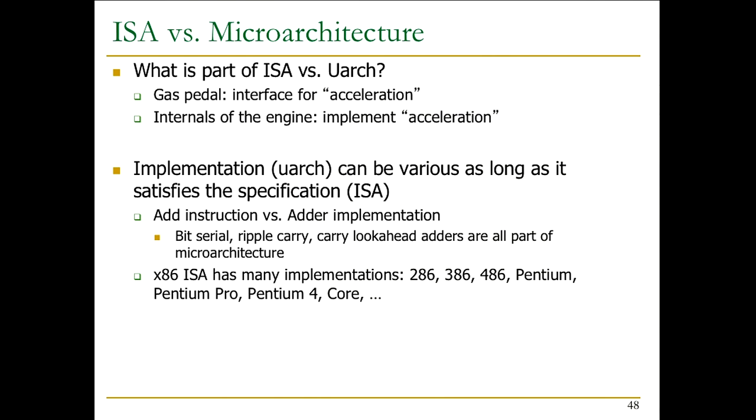It's very efficient in terms of circuit because it's small, right? But it takes time. So the trade-off you're making there is it's a small circuit, probably efficient in terms of power, but then it takes 32 cycles to do an add. This may be okay if you're doing billions of adds and you can parallelize them, right? But if you're doing only one add, you need to wait 32 cycles.